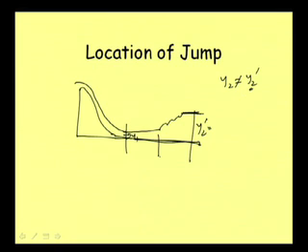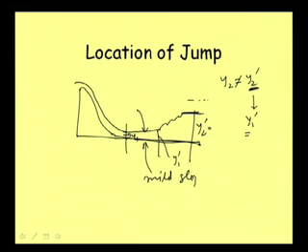If your y2 dash is less than this y2, then we need to find out where it will be located. So, how can we do this? We know this y2 dash, so from this y2 dash we can calculate indirectly our y1 dash, this particular depth. And now between this y1 dash and this y1, if this is a mild slope, then this profile will be M3.